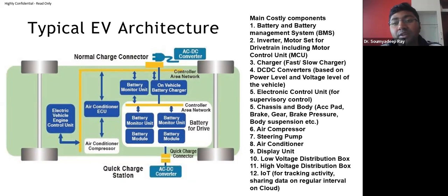Suppose the battery temperature reaches 80 degrees Celsius. The BMS ensures that the battery should not turn on even if we give the command. And it would show on the monitor or some kind of display the fault: high temperature reached in the battery. So that ensures, okay, a high temperature fault.